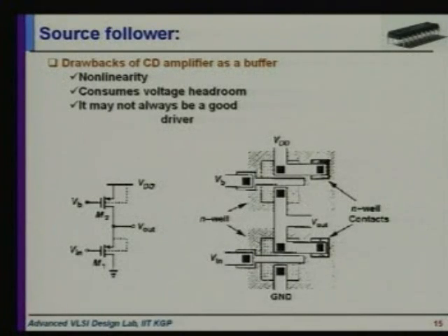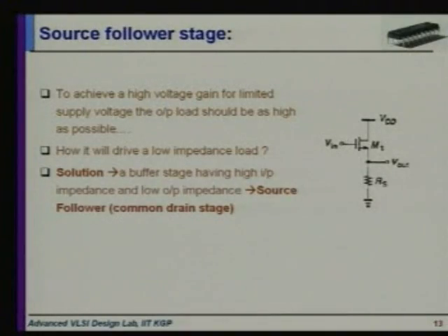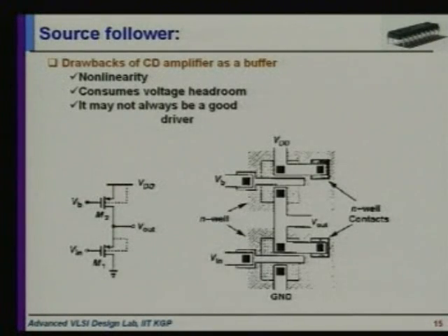Okay, see in the previous slide, there is a problem with that source to bulk voltage. There is a problem with the nonlinearity with the VTH constant. So we can readily alleviate that by using VB. See these two, NMOS and PMOS, that is called the push pull type of amplifier, where we are using both.